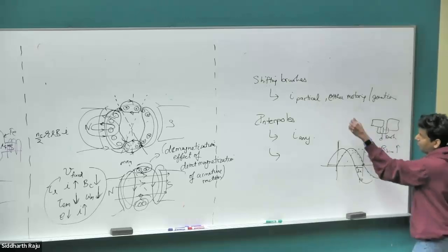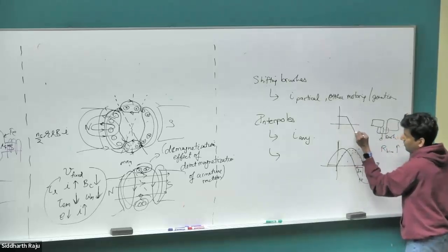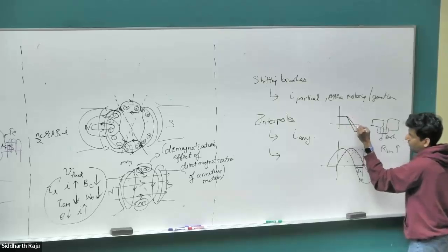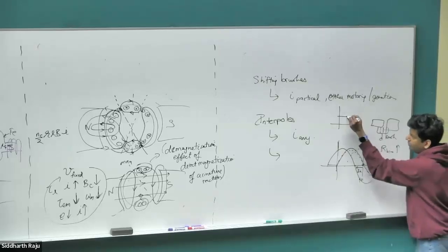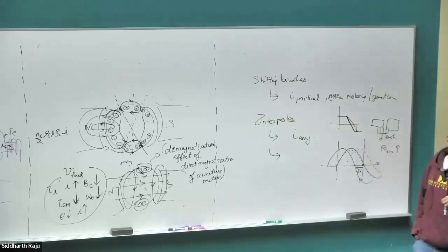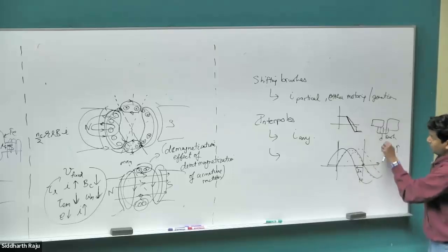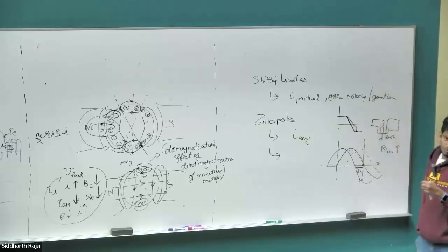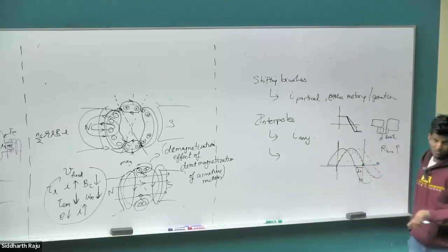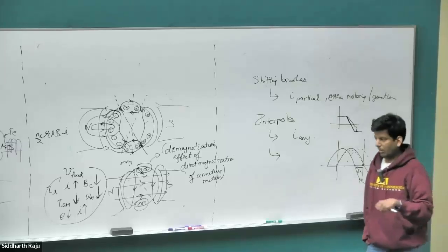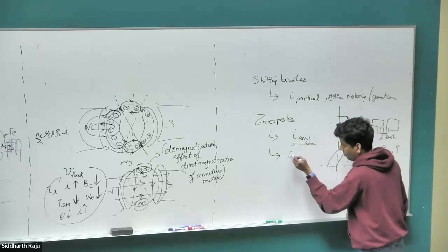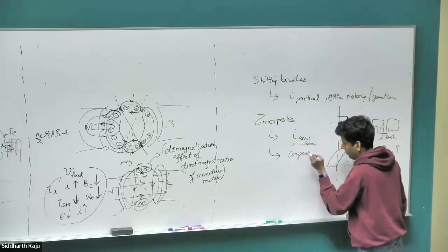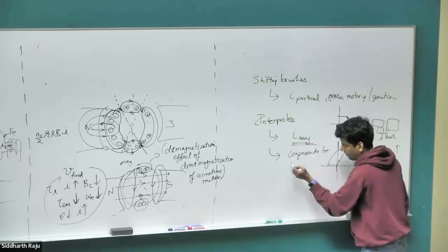Even if you use the resistive graphite brush, as we saw on this curve, it would still have some component of current that is not quenched fully, right? You can quench that component fully and make it go to have a full proper commutation by using this. But that will come at the cost of having a slightly larger amount of circulating current going through the coil that's being commutated, because there is some amount of voltage that's being put at that point when it's being made, right? So you can not only do for any current, you can also compensate for L dI/dt.